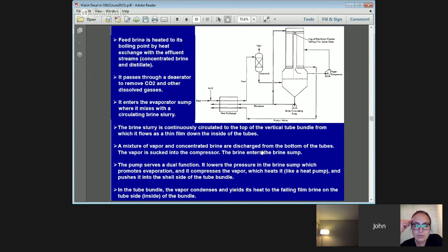So I thought I'd take some time to go through mechanical vapor recompression, which is shown schematically here. Now this is true evaporation technology. Water is fed into a set of heat exchangers which capture heat from the unit. The water then goes to a de-aerator where carbon dioxide and air is purged.